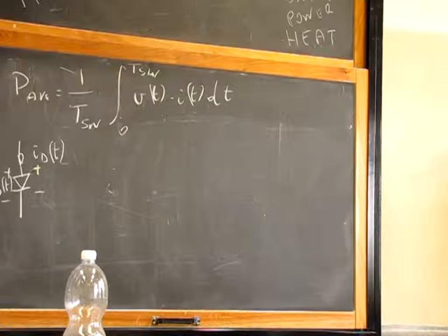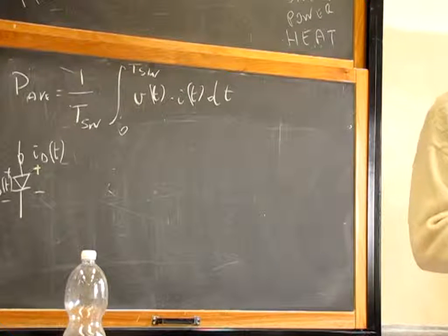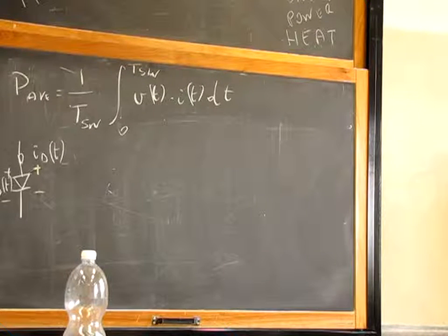Okay, tell me two things, please. First, tell me it's almost constant. And second, forget in this class 0.6, 0.7 volts. Unfortunately, it's not true. For power diodes, the normal voltage that drops across the diode is on the order of magnitude of 1 volt. You can assume 1 volt is a good choice if it is a normal PN diode, a silicon diode.